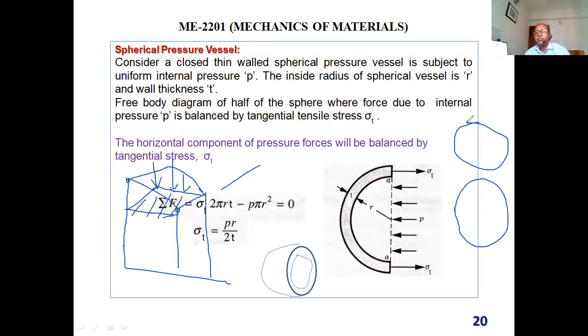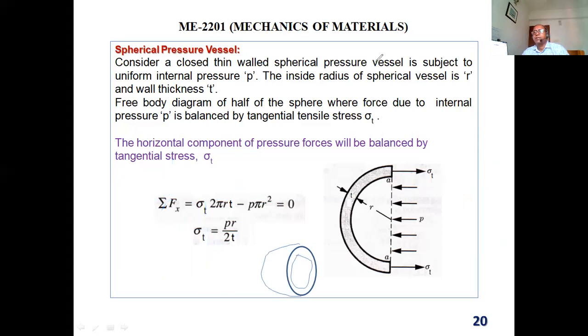So how can we figure out the force on a curved surface? You just take the projected area. For example, I see the head of the pen, and this surface is not completely flat. So how will the pressure be over here? You just take the projected area. That means this will be a completely round surface, pi r squared. You multiply by the pressure, and you will get the force. Just remember, we have to take the projected area if the surface is not flat.